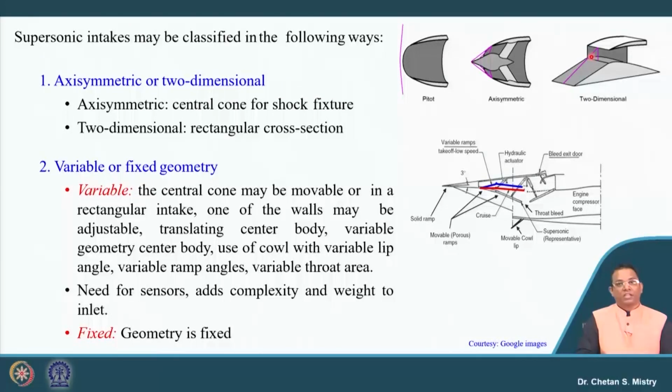So just realize that when we have supersonic flow, I need to decelerate it. That can be done by using oblique shocks, and these oblique shocks are finally terminated with normal shocks. Downstream of the normal shock the flow is subsonic. Here, suppose this is one oblique shock that is terminated with one normal shock, and downstream of it, this represents my subsonic intake.